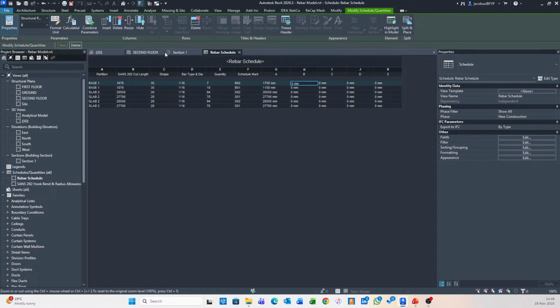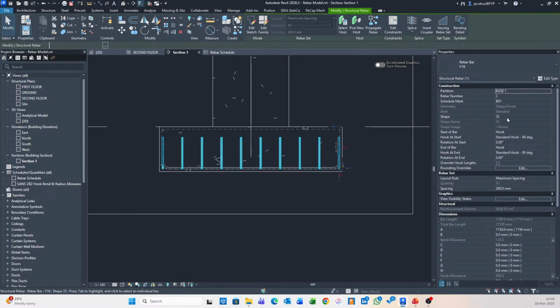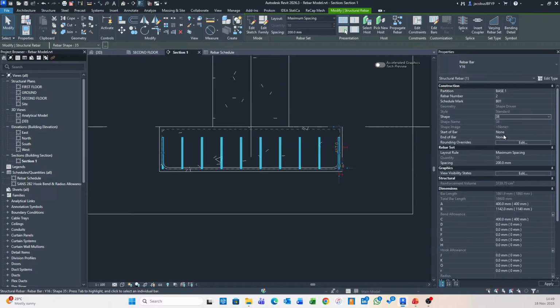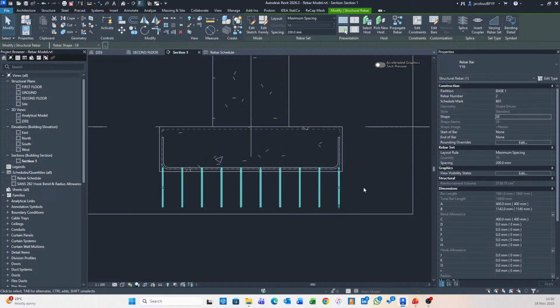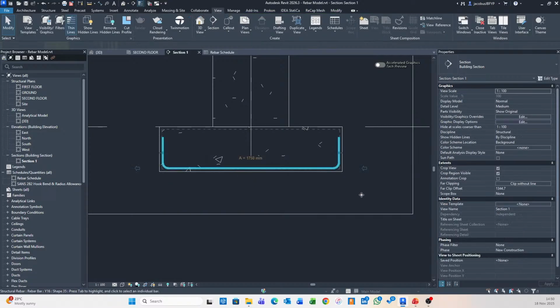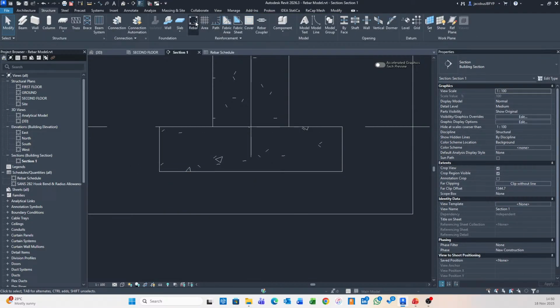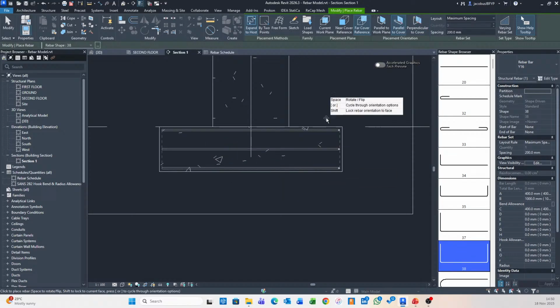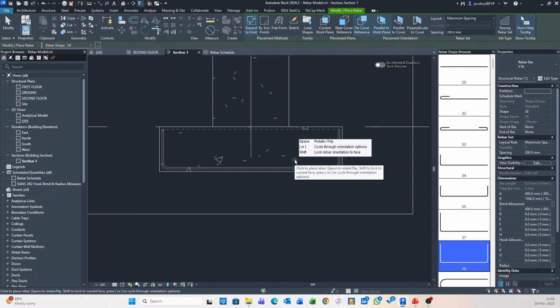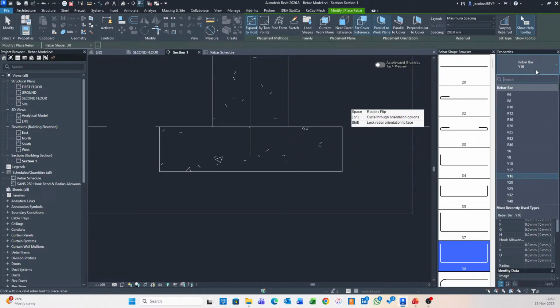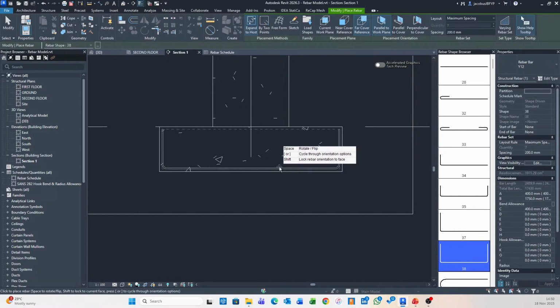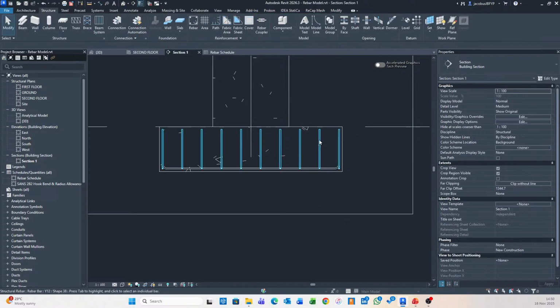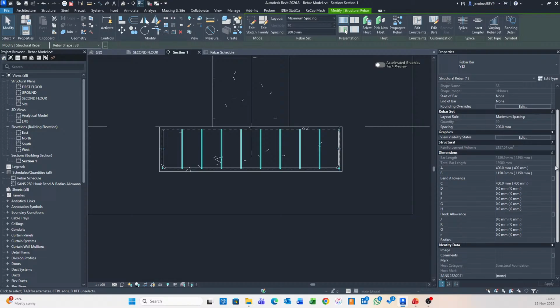All right, so let me go and modify that. These should be a shape code 38. And we shouldn't have any problems. I'll just redo them. That really isn't a problem. So I'm going to go for rebar. I'm going to go for a 38. That is what I did originally, funny enough. All right, there's that one, and it's a Y. Let me make that a Y12 rather, just so that we have different values. There we go. And then we have perpendicular to cover. Okay, so let's just make sure these guys have the right values.